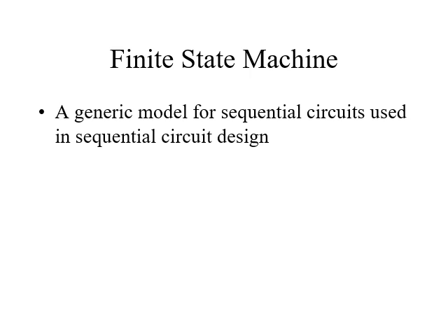Let's take an example. Suppose I have an LED. Now LED can have two states, either it is on or it is off. So the number of states is 2 here and it is a finite number of states. So this particular machine which I am talking about is a finite state machine. So we can control the output of a finite state machine by controlling the input as well as the previous outputs. So we will see how we design a finite state machine.